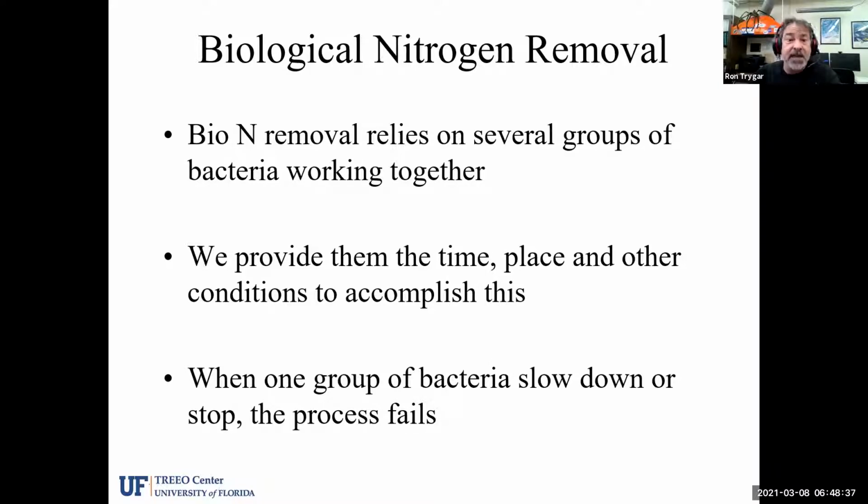We'd rather have that nitrogen gas conversion in a controlled environment, maybe in what we call an anoxic tank. So when we have an anoxic tank working properly and we're getting the conversion of nitrate to nitrite to nitrous oxide and then finally to nitrogen gas, we actually release the nitrogen in a controlled environment back to the atmosphere, and we produce a little bit of what's known as alkalinity.